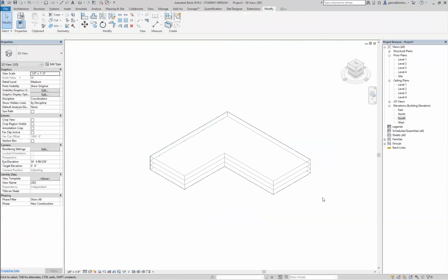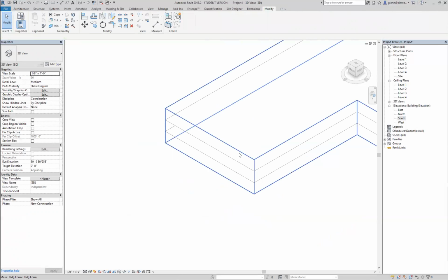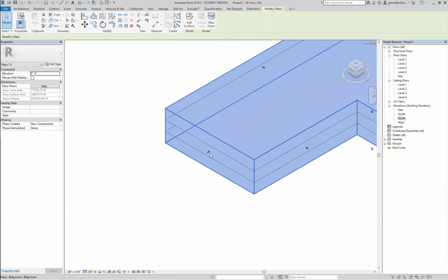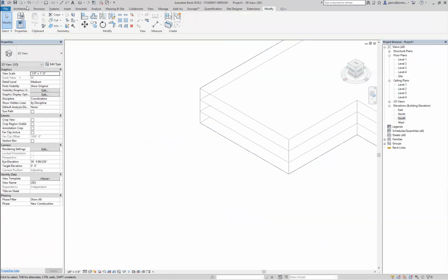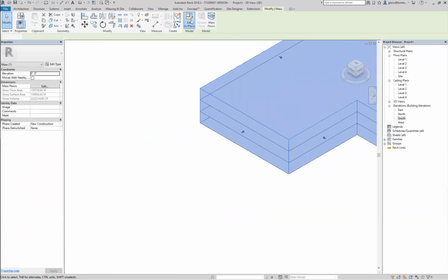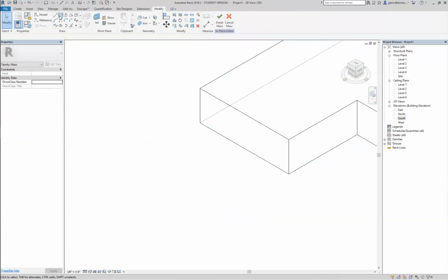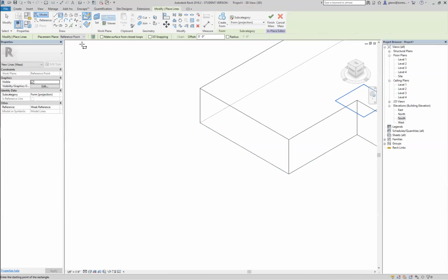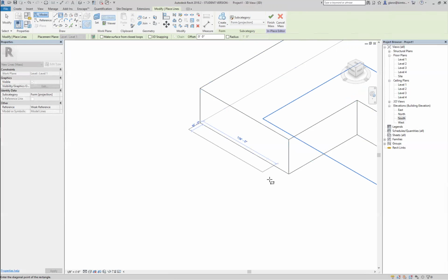What I was going to address was the whole issue of, what if you actually want to have separate amounts of floors in different parts of the building? And you can do that. Let me zoom in there and show you what that might look like. So for example, if I wanted to have a big multi-story atrium here on the end of the building, I might push that back a hair. Then I'm going to go back to the mass. On level 1, I'll see if I can draw another rectangle in here.